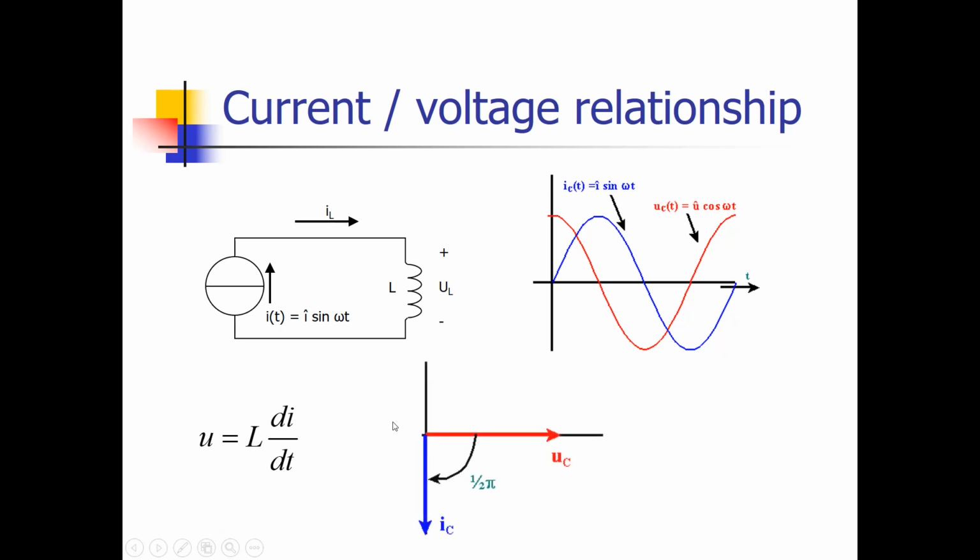What we can also do is put these in a so-called vector diagram or phasor diagram, in which we only express the amplitude of the voltage and the amplitude of the current. Suppose we put the voltage on the horizontal axis over here, so the top value is put over here. Then we have to put the current on the negative y-axis, because the current lags the voltage by 90 degrees, as we can see over here.